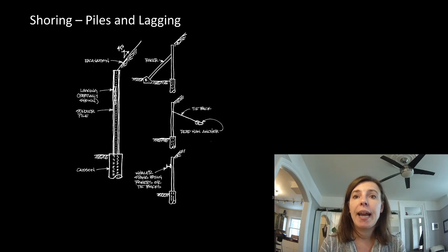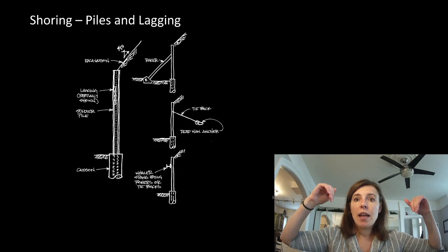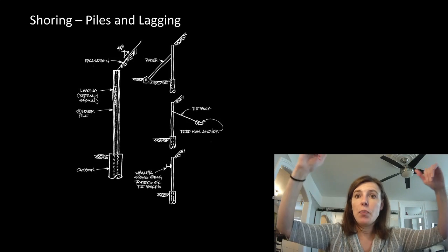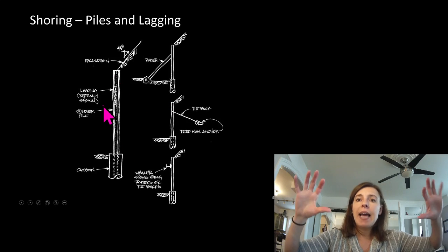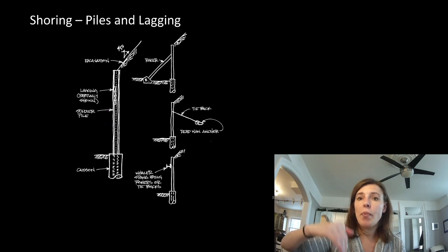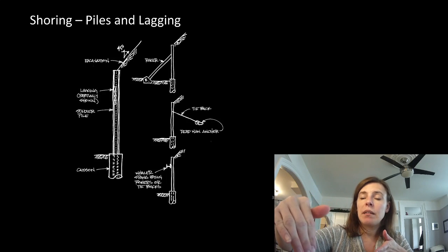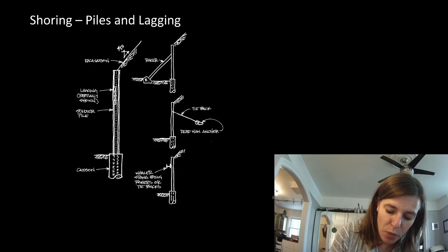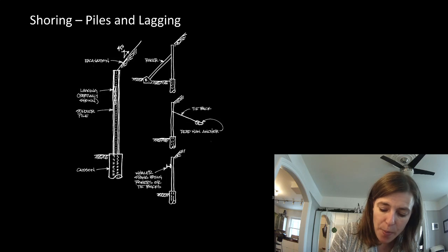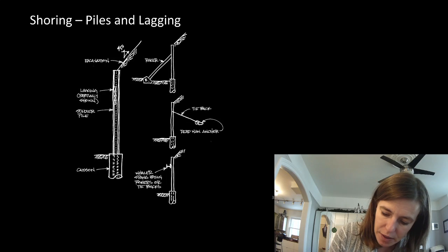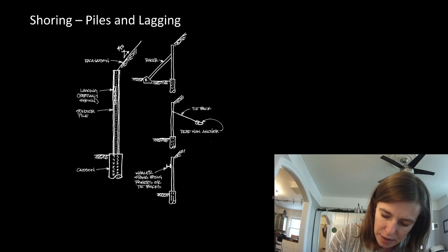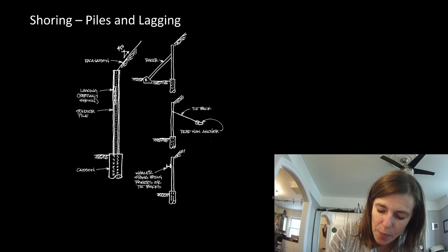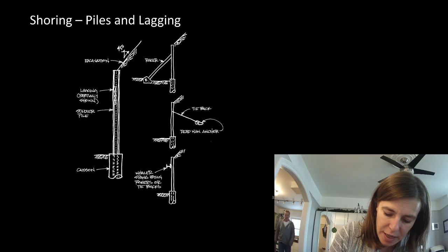The way they do that excavation is they dig down 4 feet, and they drive a series of piles, so that would be our steel elements, and then they dig out 4 feet of soil, and they drop pieces of wood in between those pieces of steel. So if we were looking at it from the top, and this is a really bad drawing, I apologize.